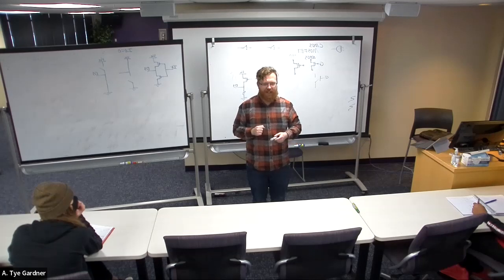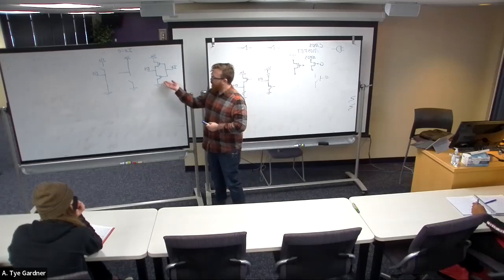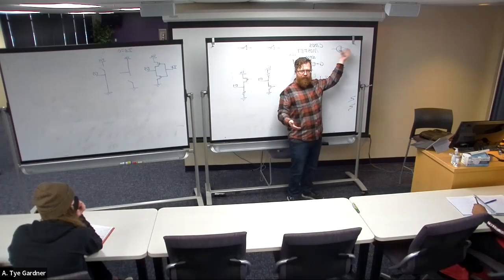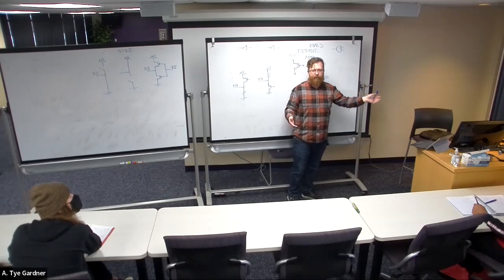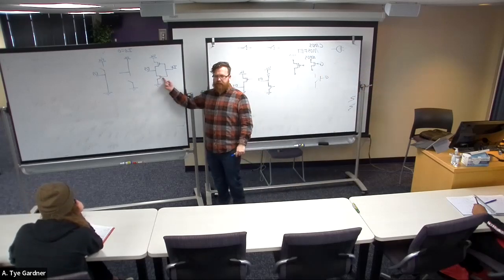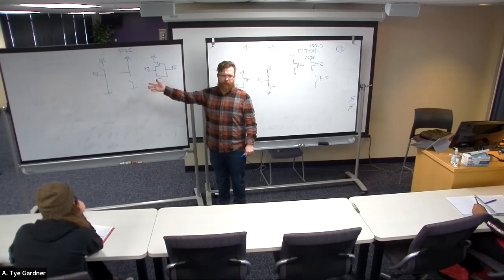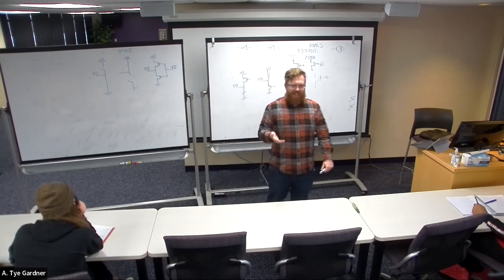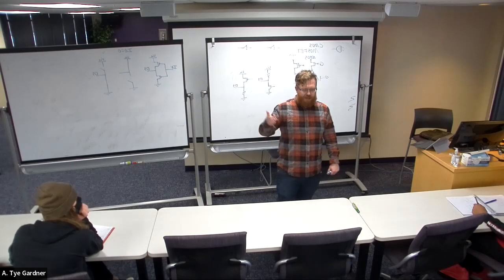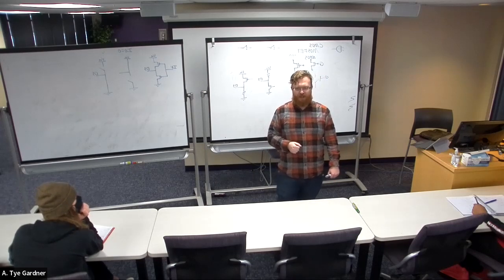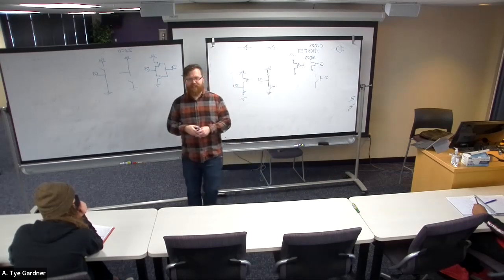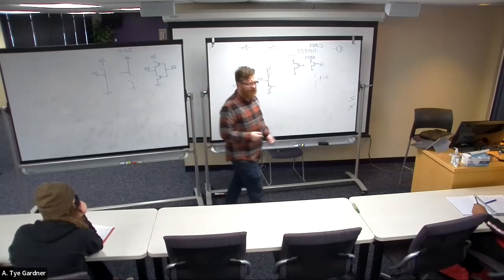They're getting tiny. And now the issue is that these gates, remember how I say in an AND gate, no current flows into this gate ideally, right? Nothing, no current, but there is a little bit of leakage. Well, that's this. They draw a little bit of current through them. It's not ideal, but the smaller we make them, the worse that gets, until you reach the problem they have now, where quantum tunneling becomes an issue, because the materials are so small that electrons can just go from here and appear over here because they felt like it, essentially.